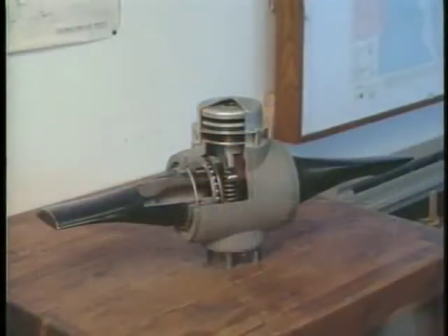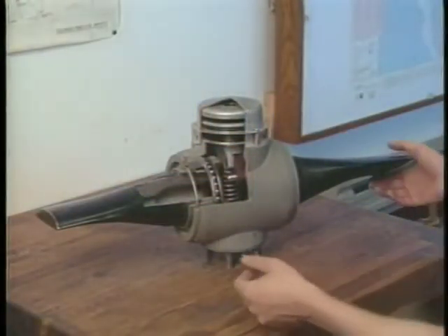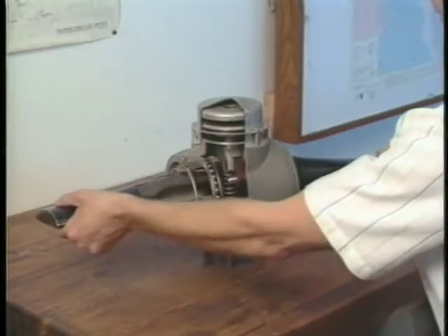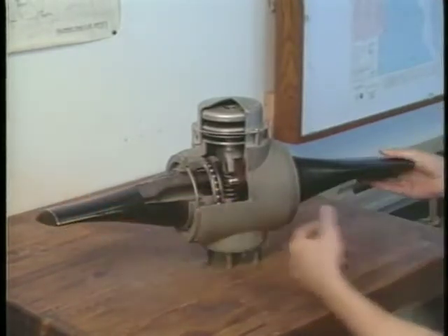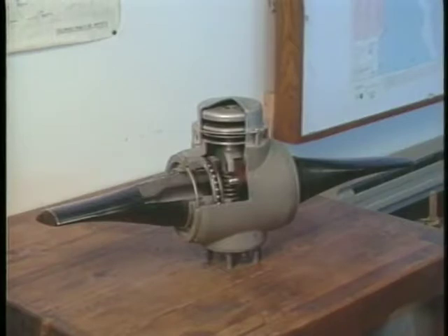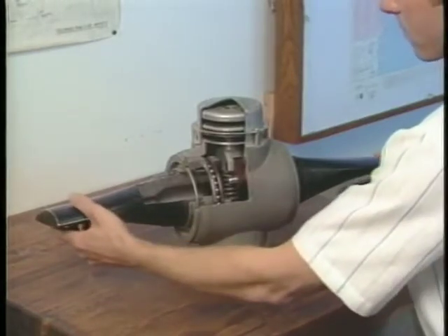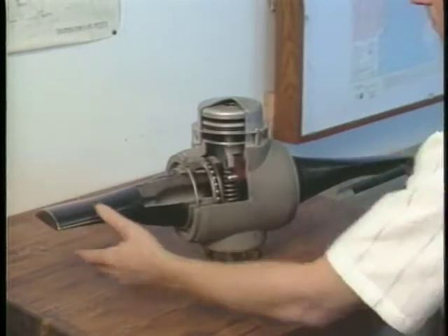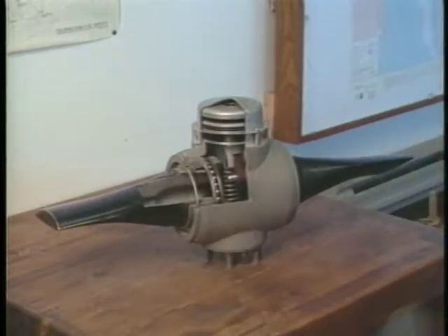The propeller hub houses the propeller blades, which rotate on a set of bearings, and a piston, which when pushed by oil, causes the blades to rotate to a higher pitch. When oil is released from the hub, aerodynamic forces acting on the blades of the propeller will twist the blades to a low pitch.